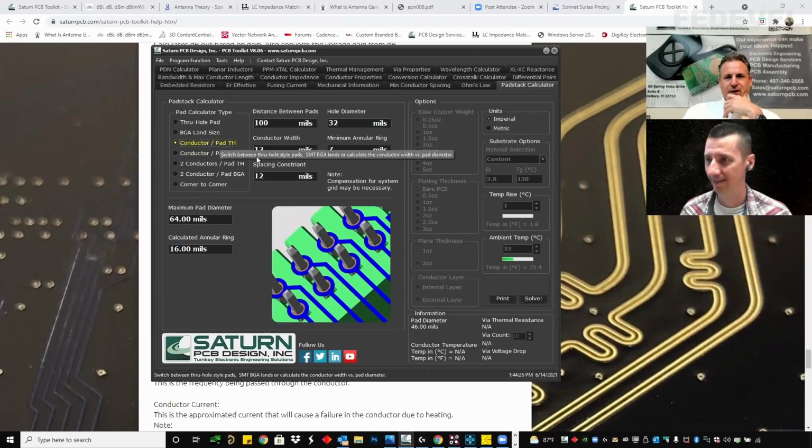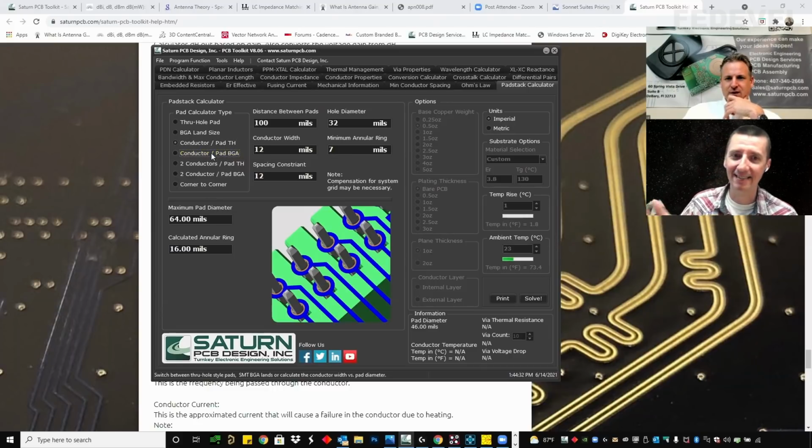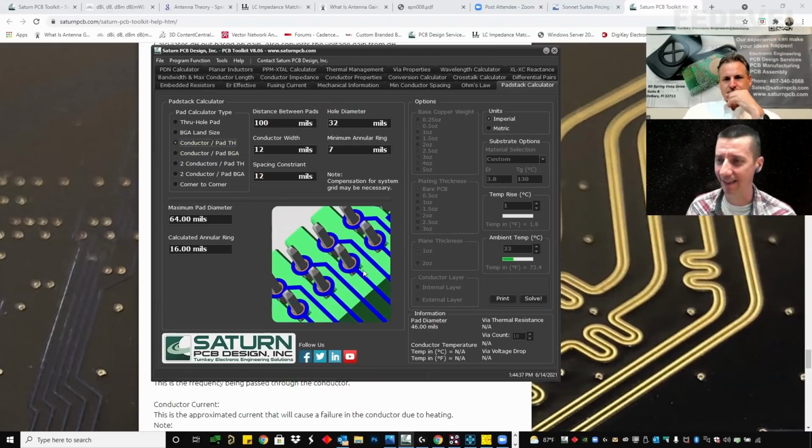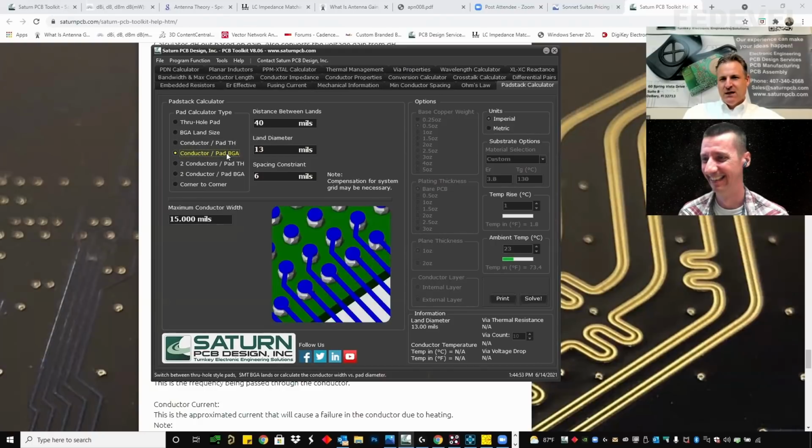And the same thing with conductor: how many traces can I fit through this? People keep asking me how I came up with the size of the path around a through hole. I always say I printed it and had a look: can I solder it? No, then make it wider. Yeah, that's what this is for. You can play around with the values to see what kind of trace you can get through conductor pins. The same thing on a surface mount basis.